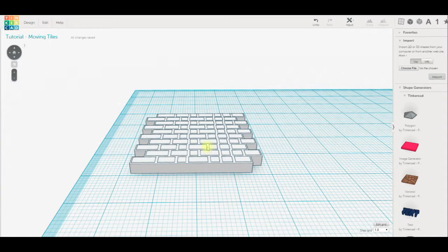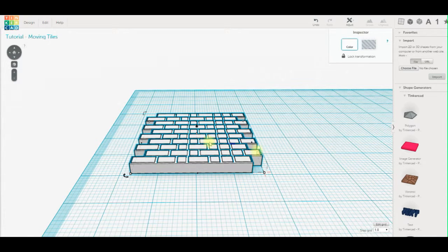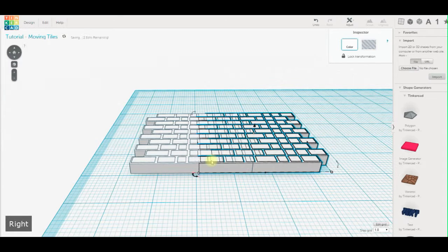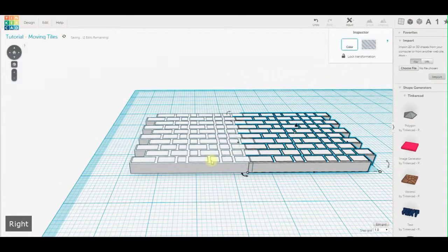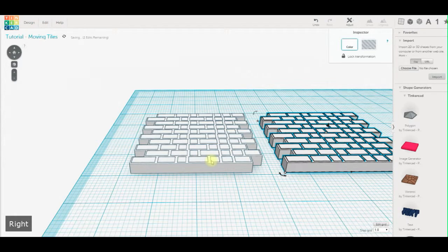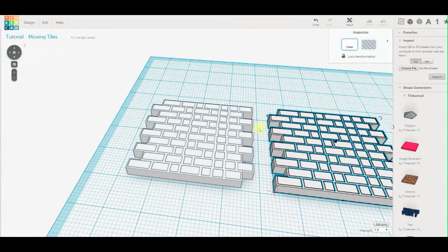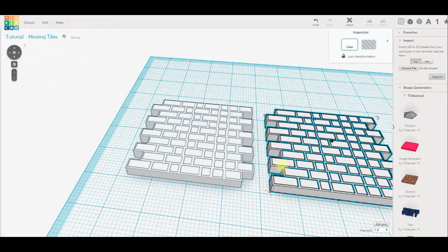Okay, so duplicating or copying parts: click a part, press Ctrl and D, and you'll see the particular area highlighted yellow. What it's actually done is copy a part directly on top of that part. Using the arrow keys on the keyboard, I can move the part right in 1 millimeter increments. I can just keep sliding across. I actually know that these are absolutely lined up at the bottom and lined up at the top for all cases. So I'm just moving left and right. Similarly, if I move down, I'll come down a millimeter, up a millimeter, left a millimeter, etc.